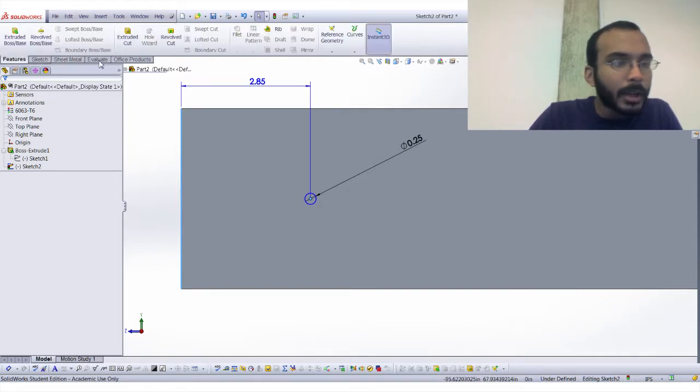And then with that, we can use this extrude cut button instead of the extrude base back in our features menu. So we have a couple more things open to us. Now that we're actually on a part, we can do cuts. So we have revolved cut and we have extrude cut. We don't have anything to revolve right now, so we're just going to extrude it.